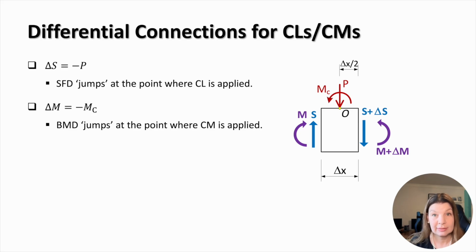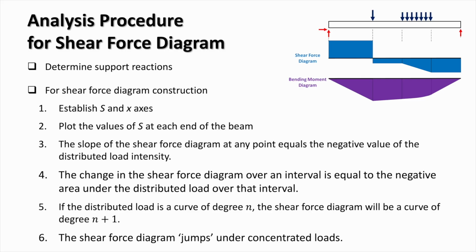where they're applied. We can now summarize a practical procedure for constructing shear force diagrams. The first step is to determine the support reactions using equilibrium equations. Next, we establish the shear force and beam length axes and plot the known shear force values at key points along the beam. The behavior of the shear force diagram can then be determined using the differential and integral relationships developed earlier. The slope of the shear force diagram is related to the distributed loading, while changes in the diagram are related to the area under the load distribution.